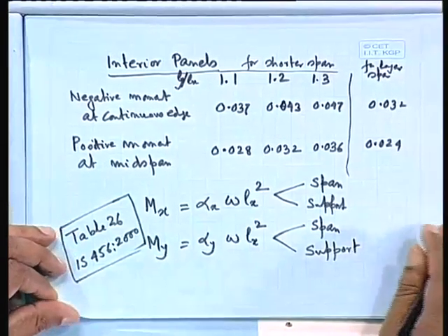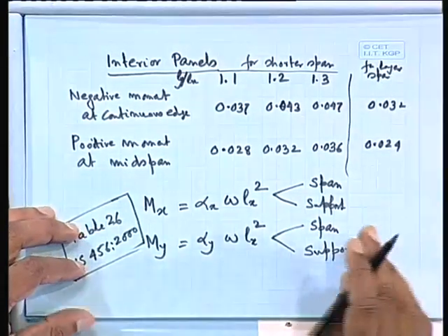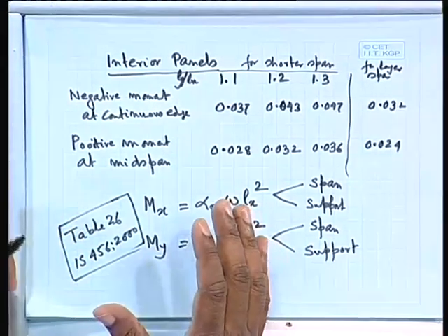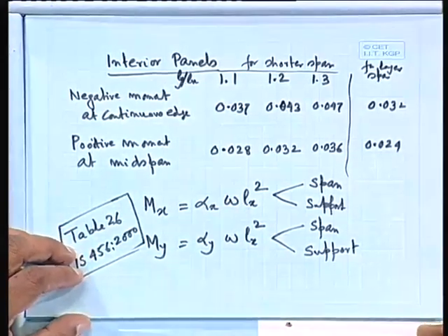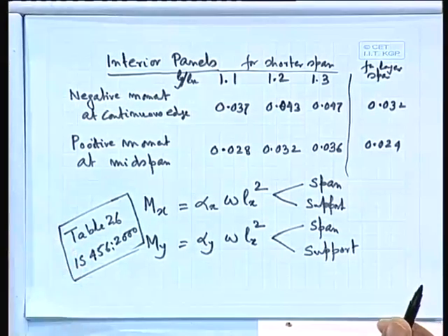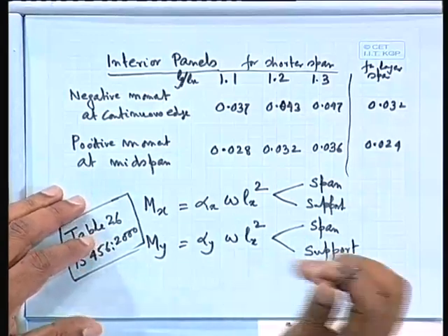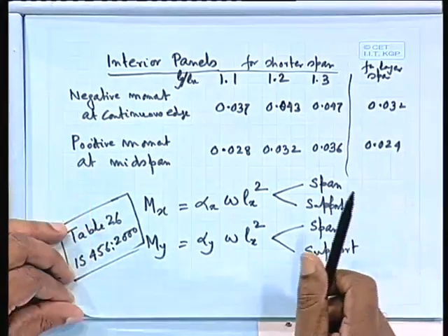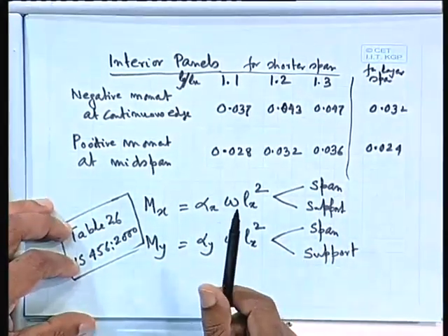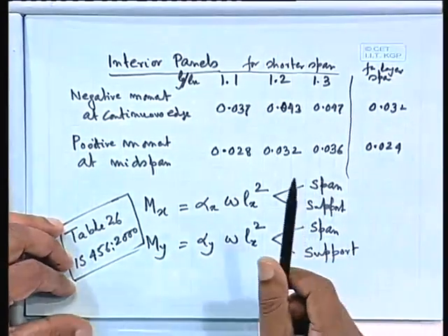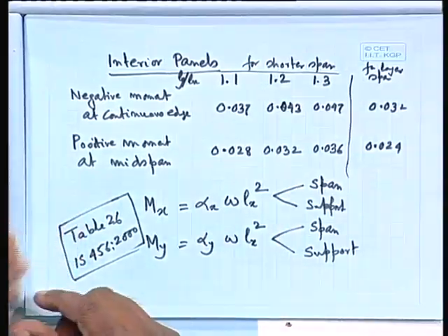These values one can calculate. When I am doing computer-based design, one alternative in the initial stage could be that I simply put the table, find out at what interval Ly by Lx is coming, and then do the problem. But I shall show you another example possibly in the next class, where we shall take the concentrated load, the one I have told in the simply supported case.